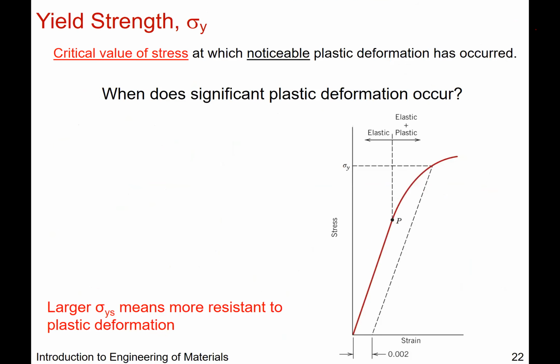Okay, now let's go over the definition of yield strength itself. Before I said, let's eyeball a linear region. If everybody did that, we would be all over the place, right? There wouldn't be a standard protocol for measuring yield strength. So the exact definition for when your material starts behaving from elastic to plastic is where we define what's called the 0.002 offset.